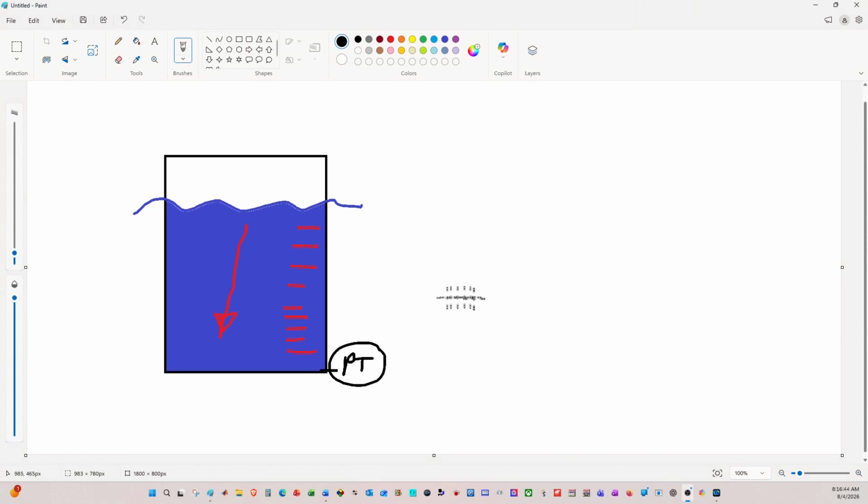If I have a normal pressure transmitter, I can put it at that point, and we can take the measurement. If you happen to have a DP cell or a differential pressure transmitter, then the low pressure side just needs to be open to atmosphere, which means it's actually going to give you a gauge pressure, and it's going to give you exactly the same measurement.